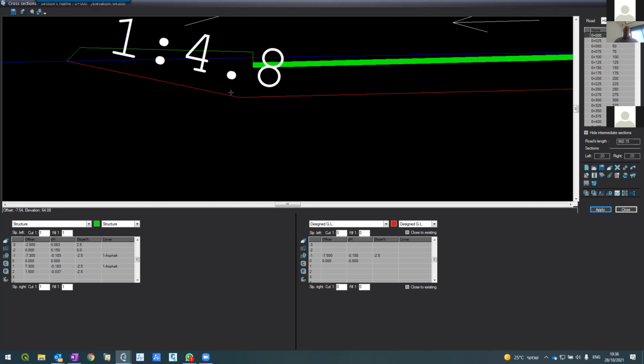20 cm inside. Now from here, I want to go by 1:1 to the sidewalk and end up 20 cm below the sidewalk top level. How do I do it? So let's calculate. Now I'm 0.5 meter below. And I want to reach 20 cm, and this is 15 cm.